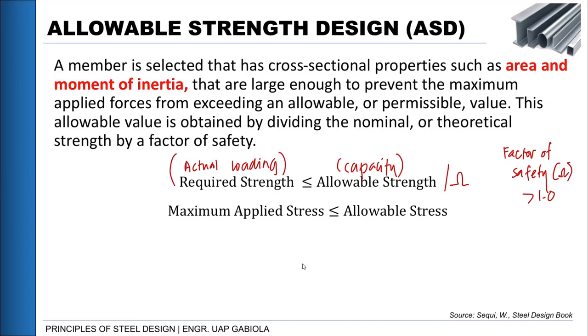Let's say for example, in a given structure, we set a value for the live load. Okay? But live load, especially for example, a classroom, let's say for the design, you are just expecting 40 students as the weight to accommodate. But in reality, more than 40 students are using your structure, or sometimes more than 40 get inside. So, it means your live load does not account for the possible overloading that the structure experiences once there is an extra number of students present in our room.